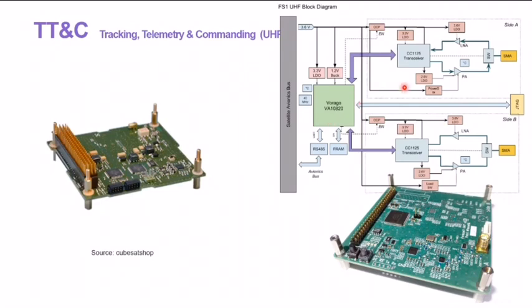If we want to design the subsystem, we need to think about the RF front end design, both for transmit and receive, because the TT&C subsystem has to take care of both the uplink, from the ground station to the satellite, and the channel from the satellite back to the ground station. So with two channels, you have to design your RF electronics accordingly. If you are good at electronics, RF electronics, this can be a subsystem for you.